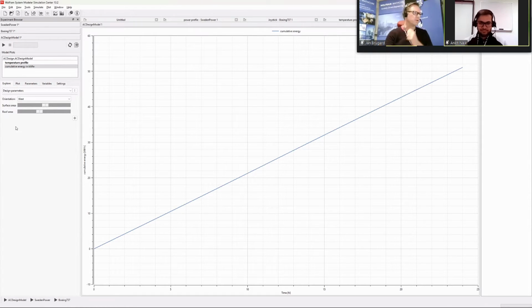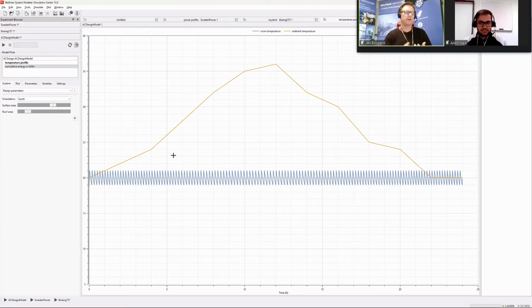Right, good. So if we look here, we can change things. Right now it only has one window on this floor that we're looking at, but we can say put it to the south and then it will change slightly. Apparently this didn't make a substantial difference. And we can slide things here and see how the different factors change behavior, and that will immediately update the results.